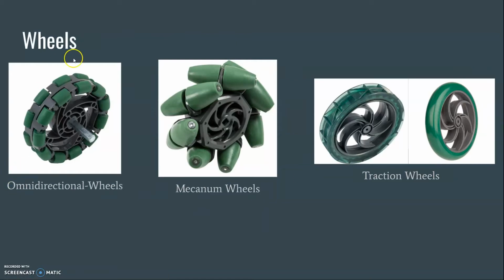So, omnidirectional wheels are perhaps the most commonly used wheel type in VEX. They generally come in three sizes: 4 inches, 3.25 inches, and 2.75 inches. Now, omnidirectional wheels have rollers running perpendicular to the actual wheelbase, which allows for better turning due to them negating turning scrub. However, these wheels make it so that your chassis is more susceptible to defense from the side.